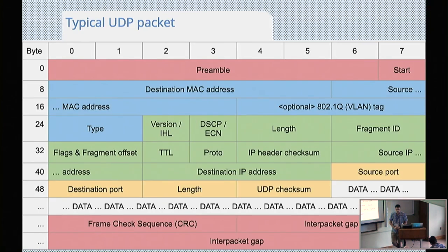But if the receiver and the transmitter have different clock rates, they do. It's 10 to the minus 6 or something. It's a crystal. It just has to stay close enough for the duration of the packet. And then when the next packet comes, there's going to be a new preamble where it can lock onto the bits. So data are self-clocking. Yeah, they have their own oscillators, and as Dan says, it's 10 to the E minus. They're very accurate. And the faster, of course, the thing runs, the better the clocks have to be.